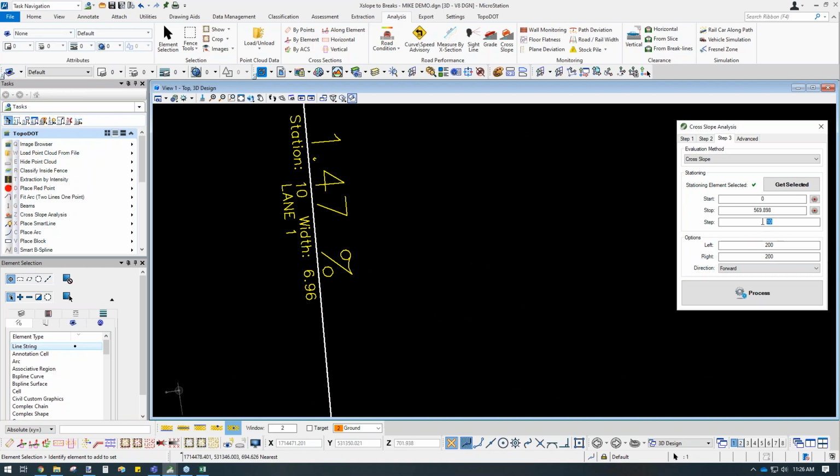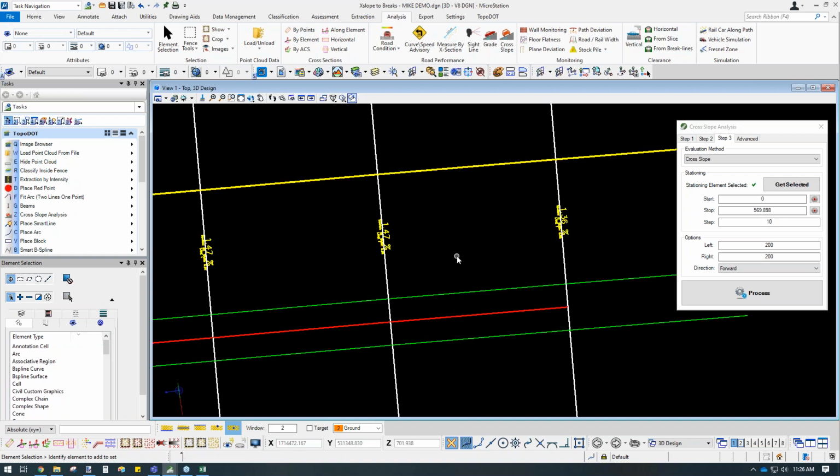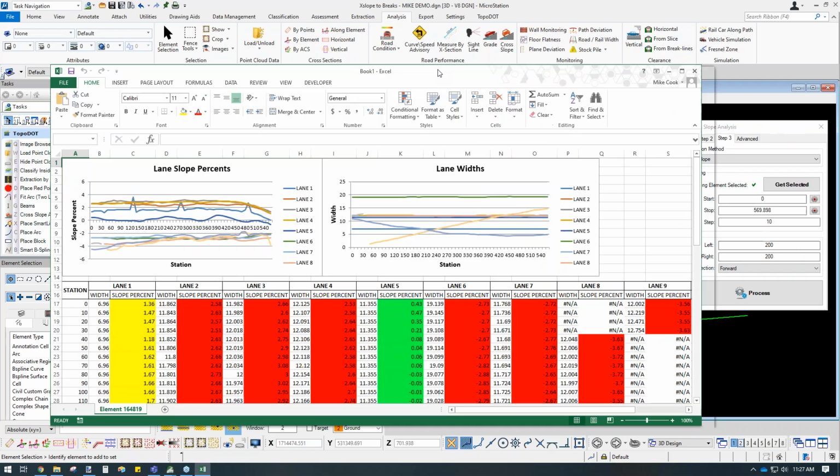10, and I want a 10-foot interval, so you can keep these synced together with your alignment line or guideline. I would recommend, if you're using an alignment line, to always start at a whole number. As an example, start off at 800 and go to 1200, and keep a nice step size that will allow you to sync up with that, like 10 or 25 or something like that.